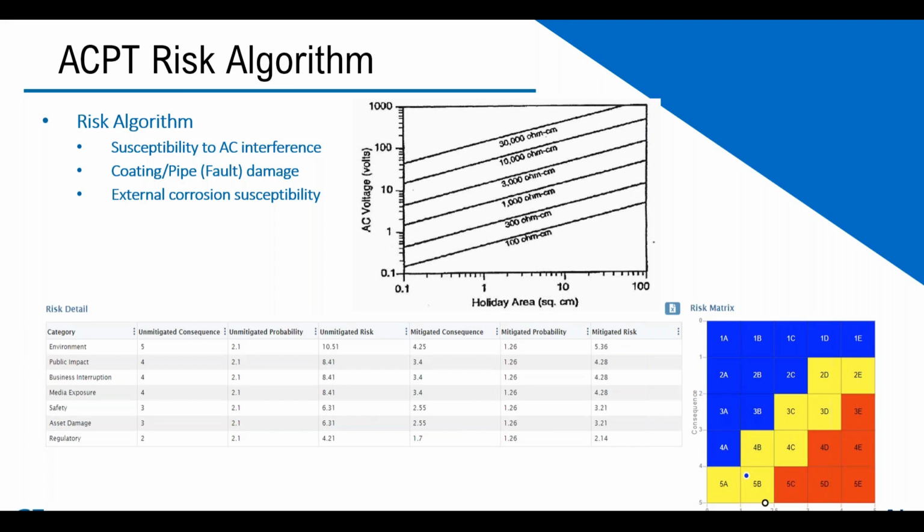So resistivity plays a role, but you could also use some basic information just to get a pre-assessment of, is there a likelihood of metal loss? Is there a likelihood of high current densities on this line? Another example is several companies, and they know who they are. Within 6 months of installing a pipeline, they already had leaks. So that gives you a clue of the rate of corrosion that occurred, and they're not big, large holidays or deep pits. They're very small, but the problem is they're steep and deep, and that's what usually occurs because it's so focused, that current density.